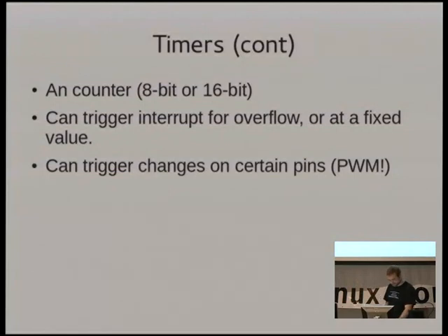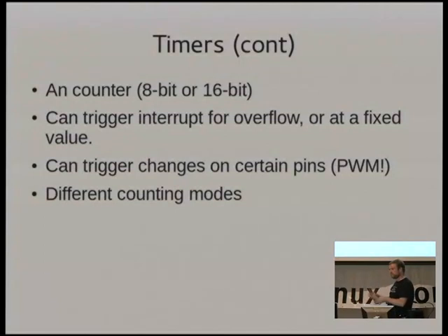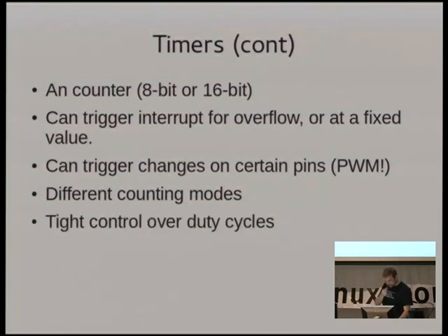As I said before, it can trigger changes directly in certain pins. That's actually a hardware function, which is why PWM is only available on some pins. It's because those pins are the ones that happen to have been hooked in to the hardware timers that are available on that chip. There are also different counter modes. The counter modes I'll get into in a second.